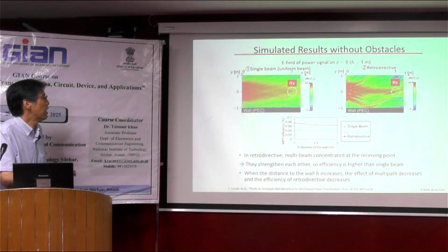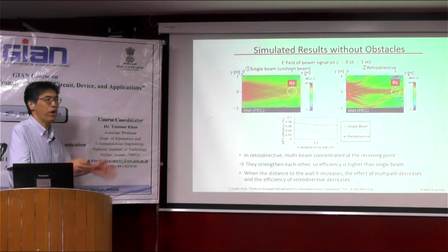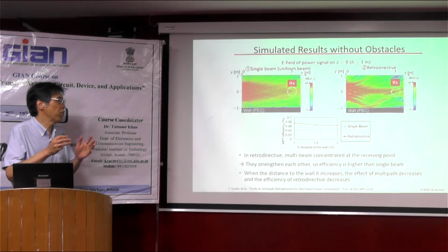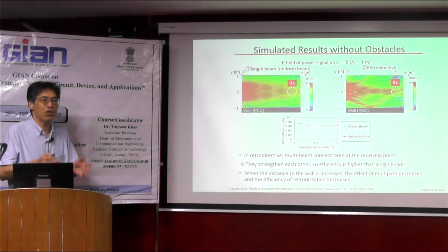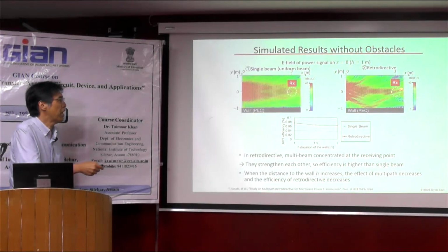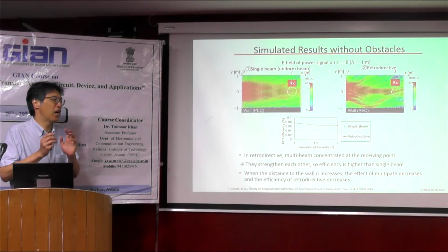If there is no retrodirective, this is an optimum beam, just the front beam only. But when we receive the pilot signal and directly recreate the phase conjugation through the merged pilot signal, as a result, we can exactly recreate the direct path and the reflected path. So I was very surprised. We can recreate the same beam form from the multipath pilot signal.